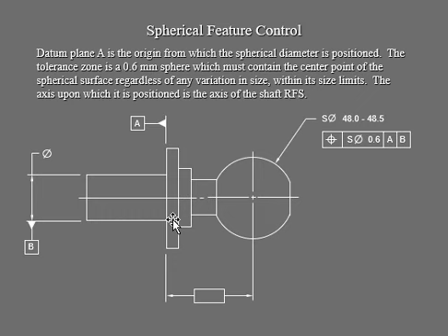You can see our feature control frame with the tolerance, your spherical diameter, which is this guy, is 0.6. Don't forget your symbols. This is the spherical diameter, that's the size of it, and this is the position. Don't forget which one is what. So position, diameter, that's the size diameter of this spherical shape on that part, the feature. And then your datums are right there, the datum reference.